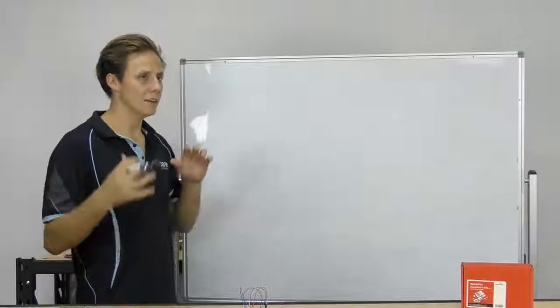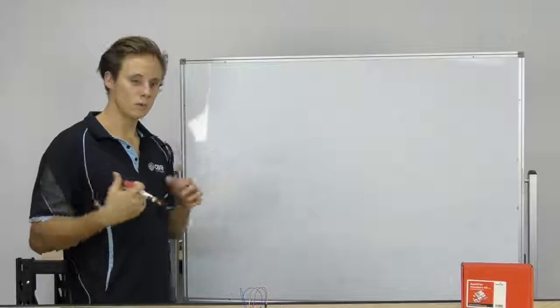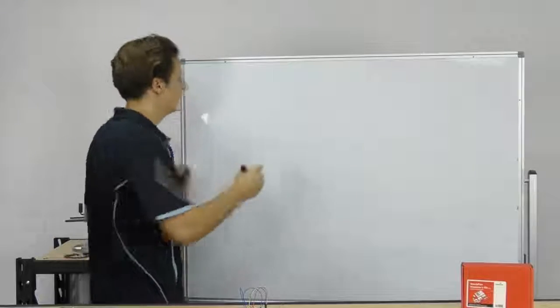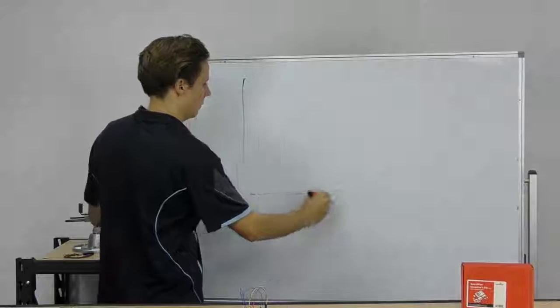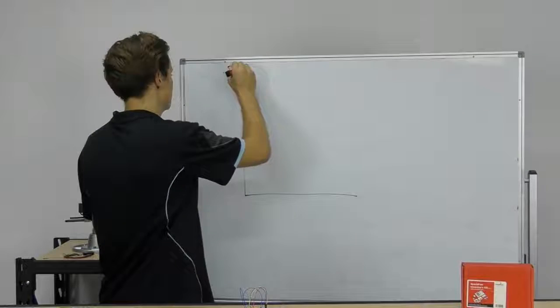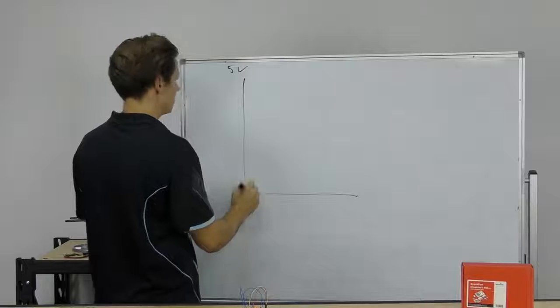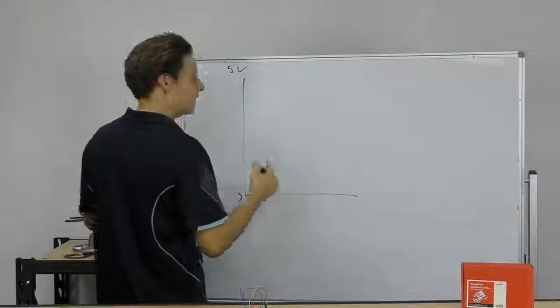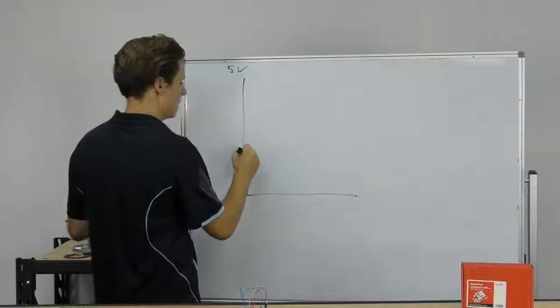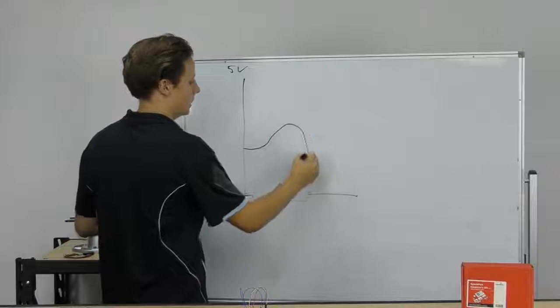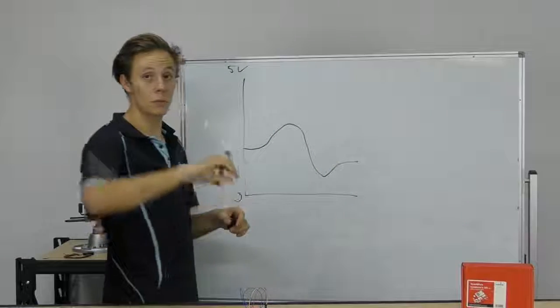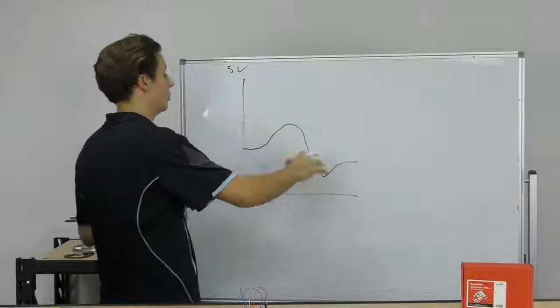A lower resolution ADC gives a rougher approximation of the actual signal, while a higher resolution ADC gives a more precise resolution. So to understand what's going on here with these analog signals and conversion and all the rest, we're going to take a look at how it actually works. So let's say on a graph of voltage versus time, we have 5 volts and 0 volts. Now let's take an analog signal. It could start here, meander up that way a little bit, down and up, and that could be you turning a potentiometer to control the voltage.